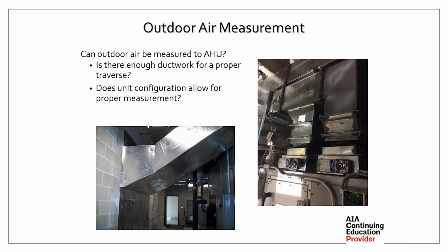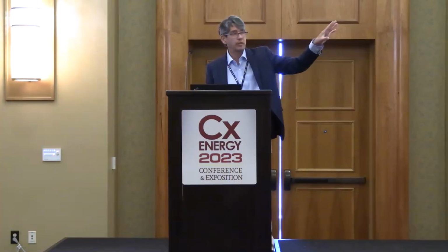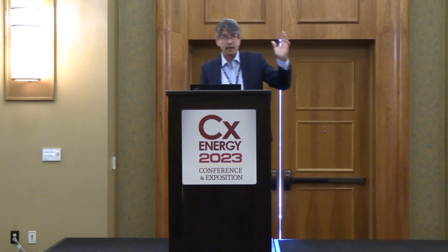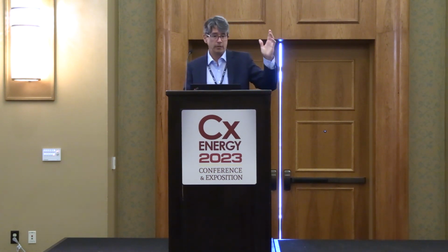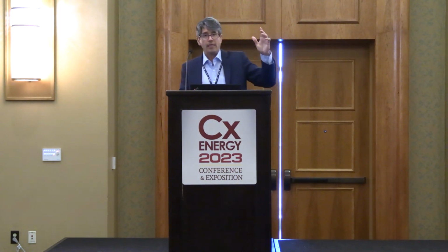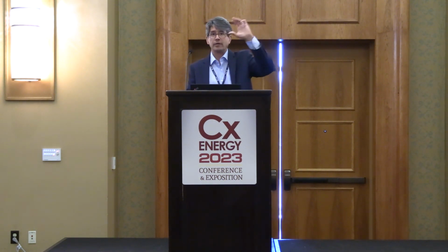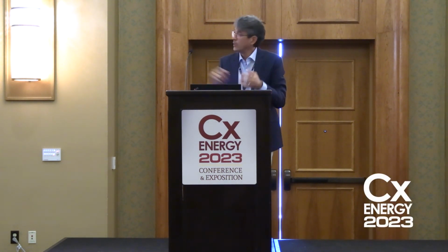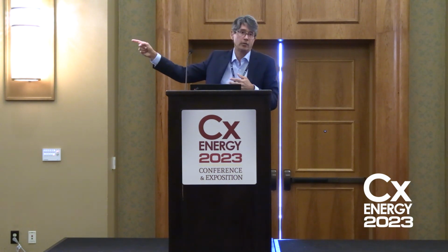Once again, our mechanical rooms are like the size of this room. We got great space between the outdoor air louver and the unit. I don't think I've ever seen it in my life, and I've only been in the industry 35 plus years. That outdoor air duct comes right out of the louver and goes right to the unit, right? We slope it up and dump it in the top. The outdoor air louver comes in. We've got, in the picture on the right, a min outdoor and an economizer outdoor connecting to the louver right back behind the unit.